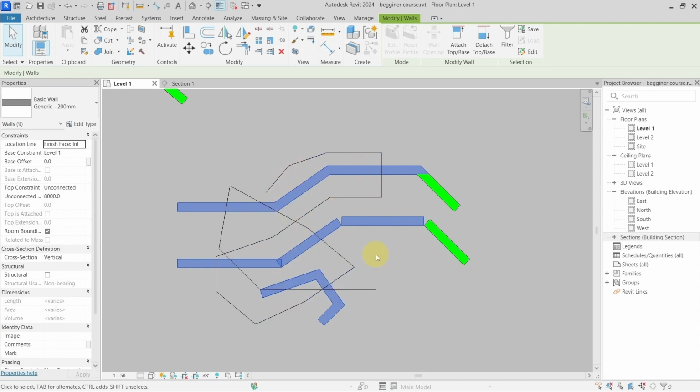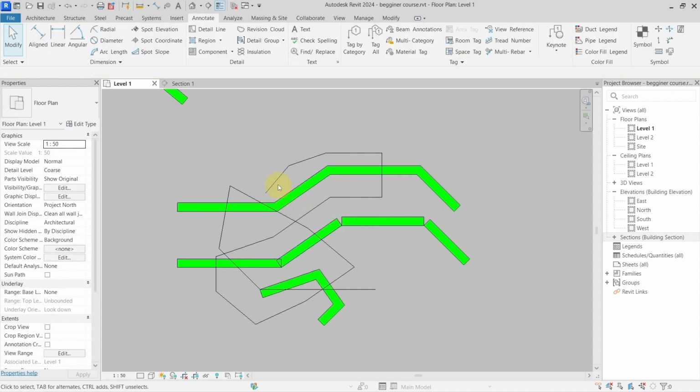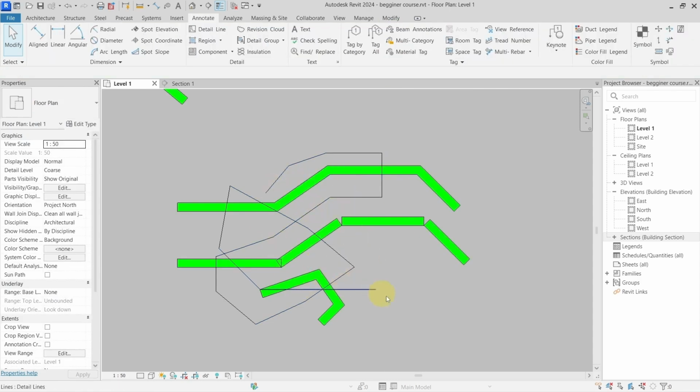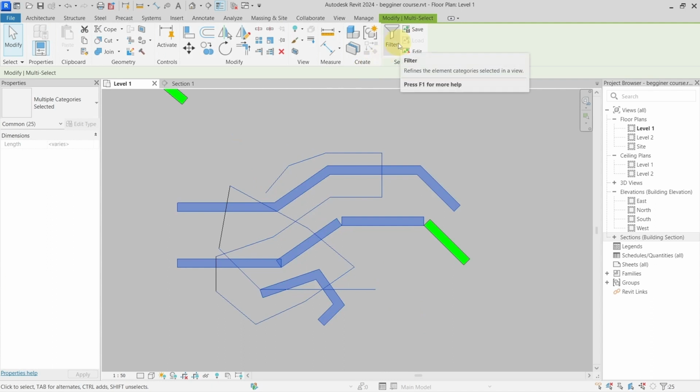Revit works in the way that you cannot tell it to filter right away, that I would say now, let's say that I want to select only walls and I will select only walls. Revit cannot do this. Revit can only filter the selection after you have selected the things. So if you select more things, then afterwards you can filter them away.